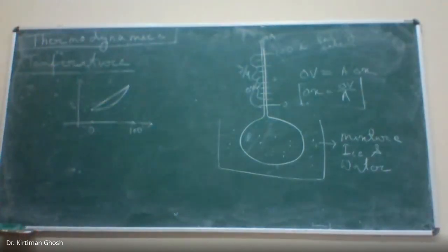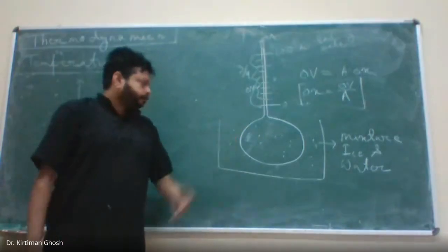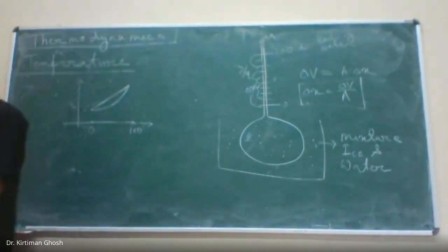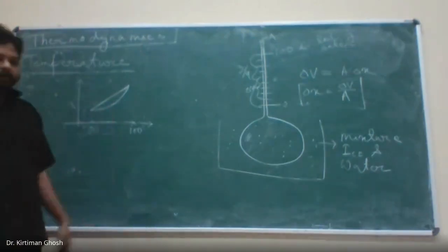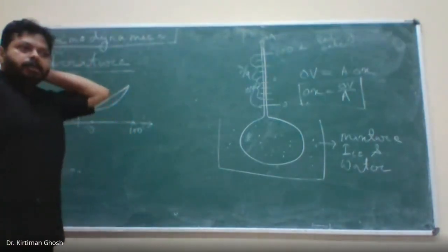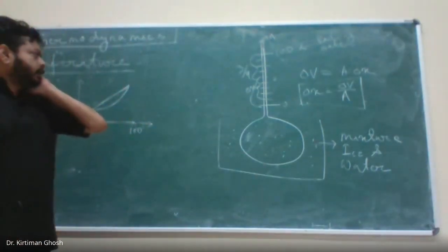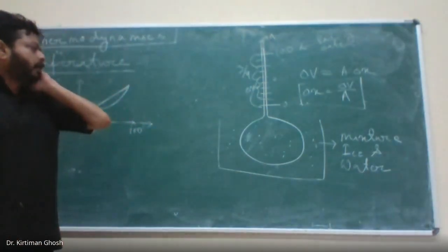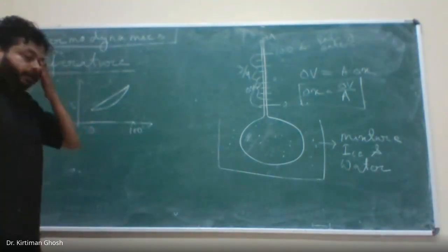So that thermometer will give a different reading for the same thermodynamic system. This is the first problem, because we do not know how this liquid behaves. We need to find out the substance which has a linear behavior. That will give us the right choice for a thermometer substance.